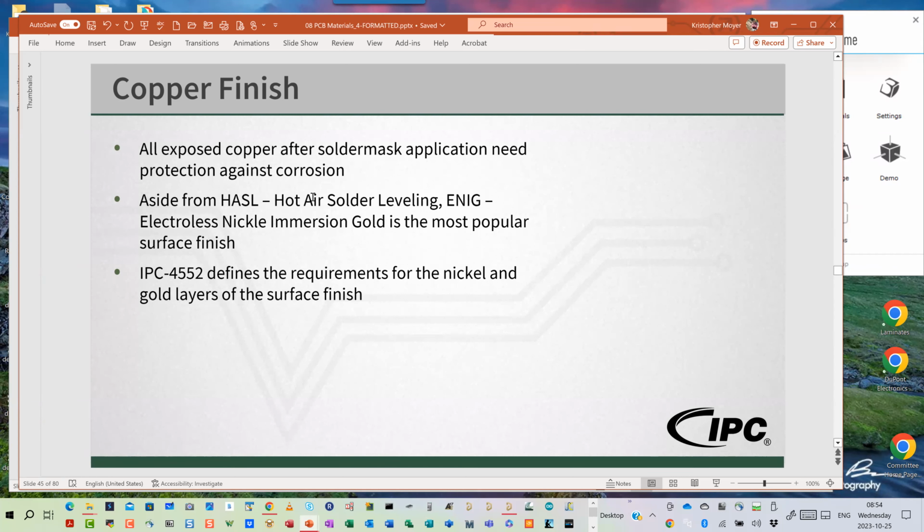And I've had people, especially from my mil aero class, say, no, ENIG is the most popular. And I would say that's true for certain market segments. For example, mil aero, where high reliability is critical. We're going to be building class 3 boards. High reliability is critical. Therefore, we'll probably do ENIG everywhere in mil aero, but they can afford it.